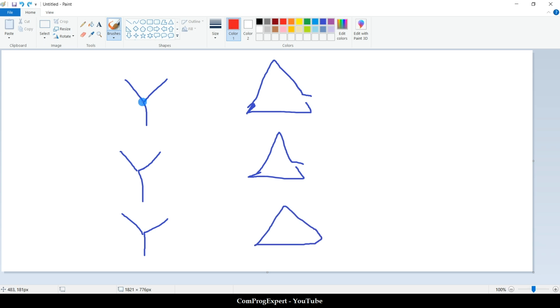So in the first case, if we connect the star point to the neutral of the supply, third harmonics are available for the phases and this voltage is 0, the summation of VA, VB, VC. If we don't connect the star point to the N of the supply, we have a voltage here. This is 3 times VA3, the third harmonic. In this case, the current is 3 times I3,